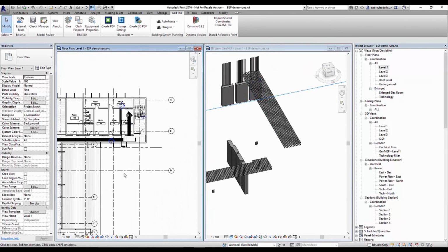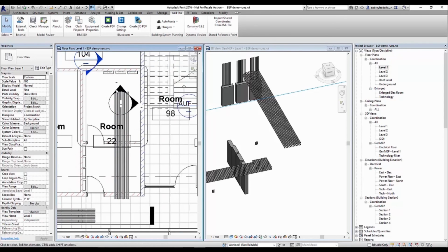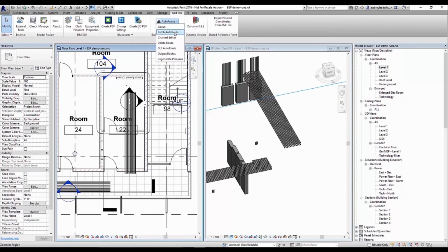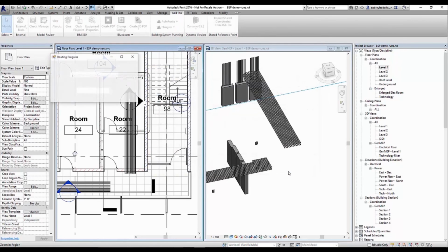So this last group of stubs, because there is this little room before our electrical room, I made this group of stubs a little bit longer so that I can fan out here at the end towards the panels. So I'm going to bring in this last batch to take us from the corridor into the second electrical room.